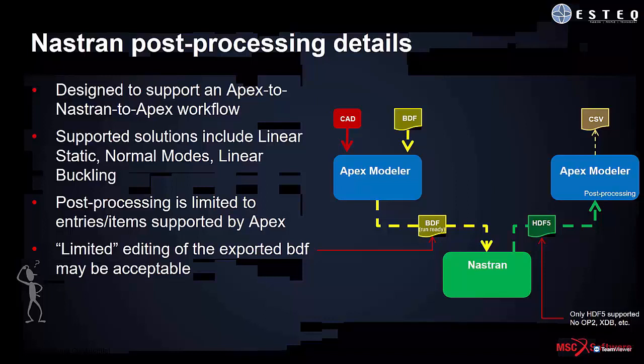One of the things why this may seem silly, but actually isn't, because Apex doesn't yet import or understand all the Nastran capabilities, it will retain those entries in the imported BDF file when it exports the BDF.